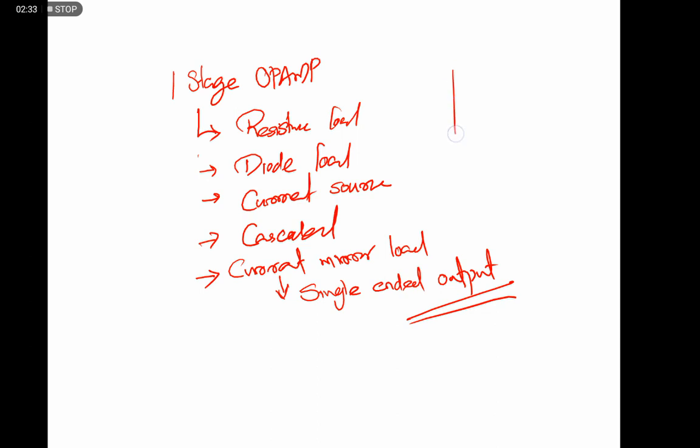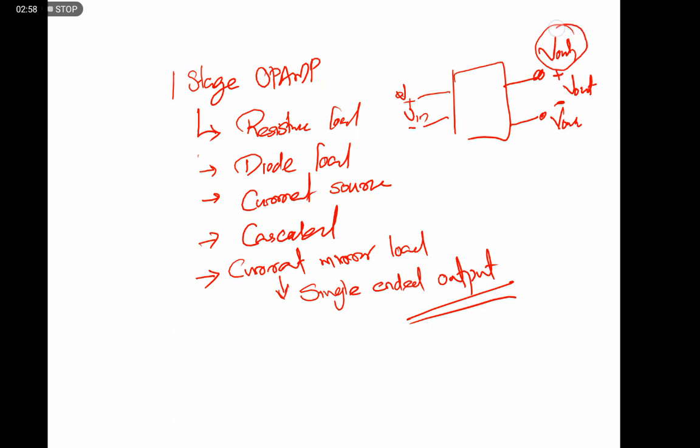For an op-amp, in the earlier case we found that two inputs are there, or we give some Vin between two terminals, and output was also taken between the amplifiers from Vout1 and Vout2, plus minus. Here we will take Vout, okay, in a normal differential amplifier. And if we take output from only one of the amplifier stages, say Vout1, we will get a gain of only minus Gm into Rd by 2. Here also it is Gm into Rd by 2. Only half of the total gain we will get if we consider output in a single-ended manner.